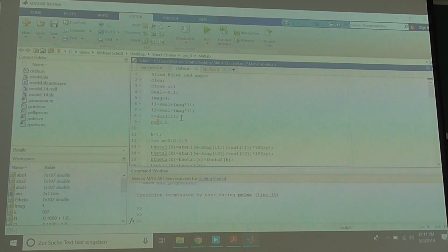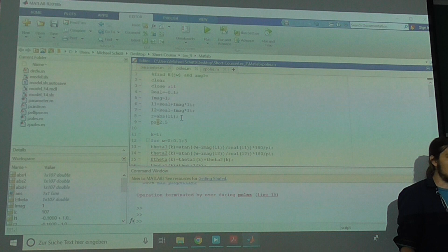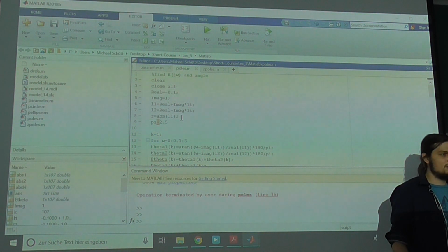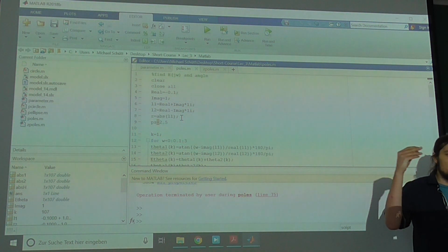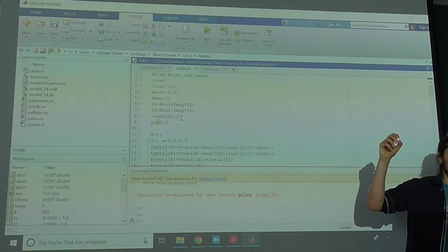But some people would, and I see this very commonly, put a square root on this, right? And then they get VDC. But what is the square root? It's not linear anymore, right? When you take a square root of a signal, it becomes nonlinear. So you unnecessarily make your system a nonlinear system, which means that it's operating point dependent. Now you can't use all the analysis that you think you can for linear analysis. They don't apply anymore. You have to do a Taylor series expansion. You have to basically try command tracking and dynamic stiffness at different operating points, and you will see that your system changes with the operating point.